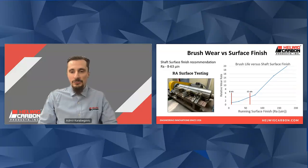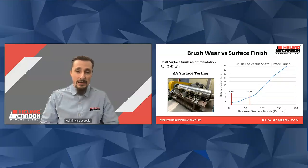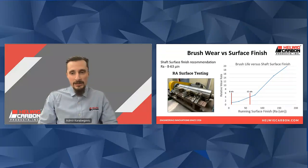There are ways to mitigate this. One would be to get the shaft surface finished back to an acceptable range, or we could reduce the spring force slightly to reduce the mechanical wear rate without creating issues with the electrical performance of the kit.